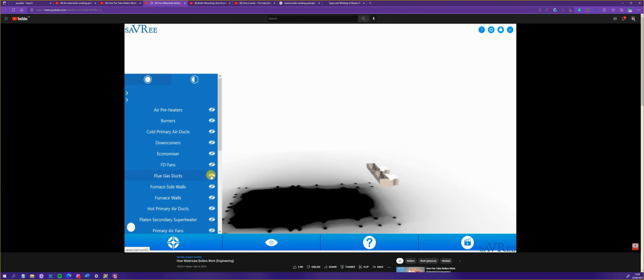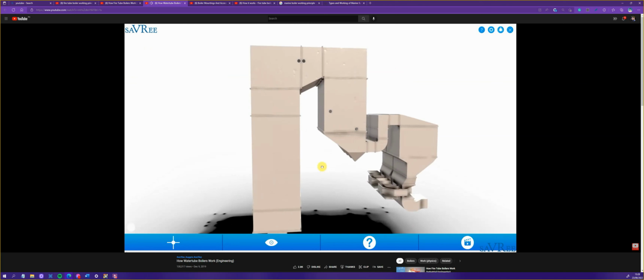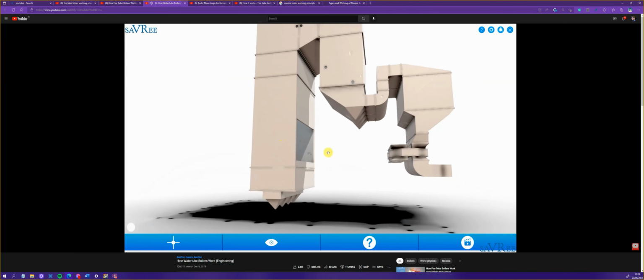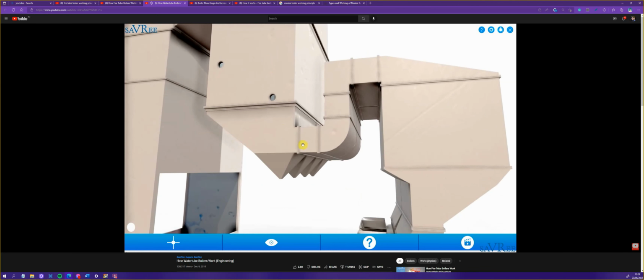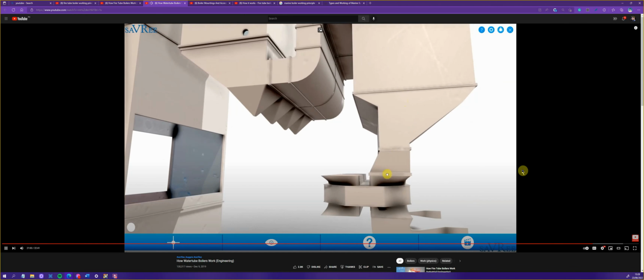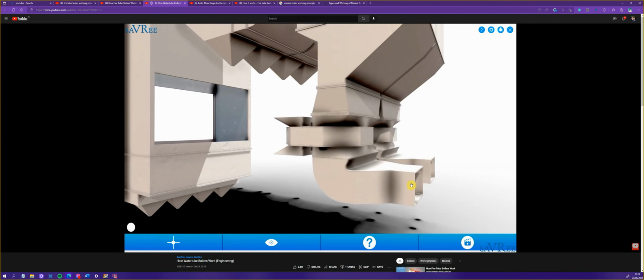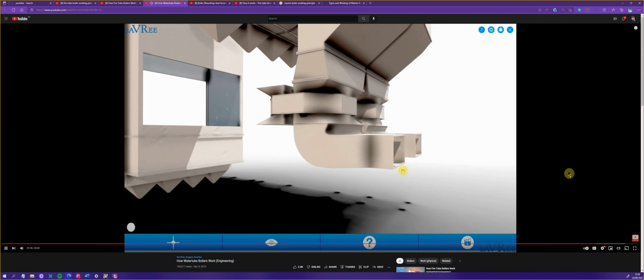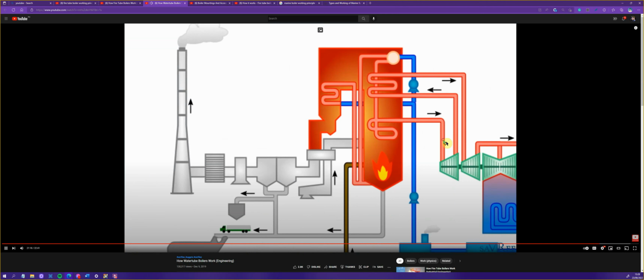And if I set up the configurator correctly, we can see that the area of combustion would be around here. Our exhaust gases are going to come up here, come across, down, and then they'll come across this way, and down here, through our air preheater, this section here, and then out to our exhaust gas cleaning system, which will usually involve some sort of flue gas desulfurization, an electrostatic precipitator, or a baghouse maybe, and then...